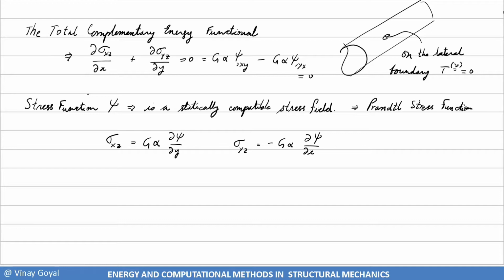So I'm able to come up with these equalities that are able to get us there. And I also want to show that at the boundary, because the traction is zero at the boundary, that means, if you recall Cauchy's relationship, which states that we have t_i equals sigma ij n_j.